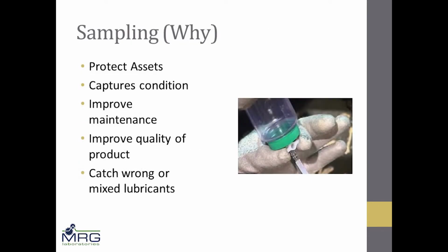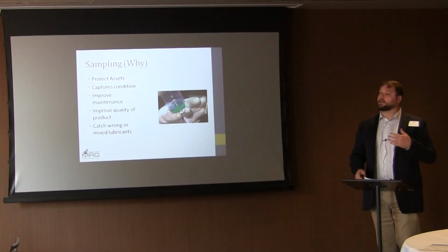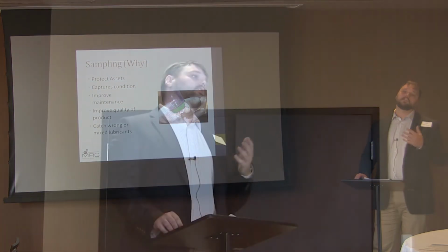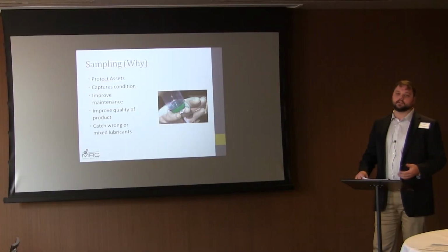So we'll start with sampling, why you should take a sample. The biggest thing is to protect your assets. If you have an important piece of equipment that is making your product or whatever to make you your money, it's going to be important to keep that running. As has been mentioned before today, if there's unplanned downtime, that's not a good thing. That means that somebody up above is frustrated, there's money that's not being made, and we don't know what to do. By sampling often, or not even too often, but just sampling your important components, you can monitor those levels, and then you can make decisions on that component, and plan ahead for an outage if you need some kind of maintenance, so that you're not having anything unplanned happening. Nobody likes that.